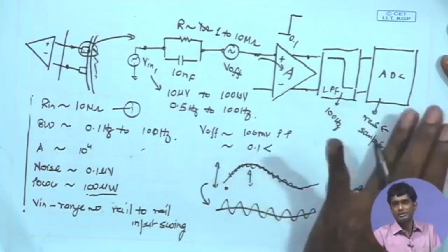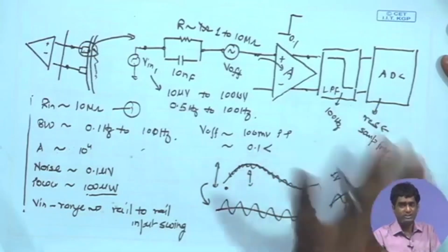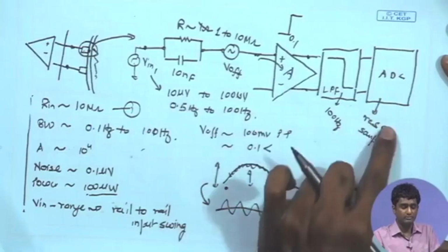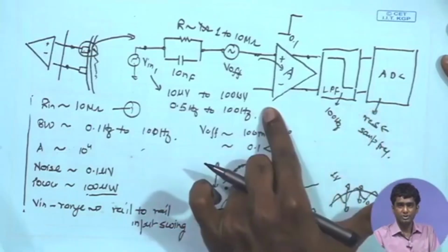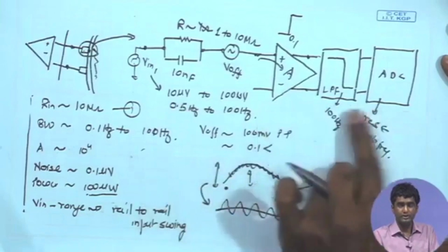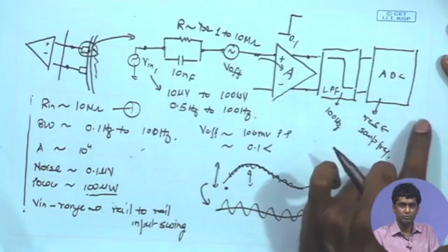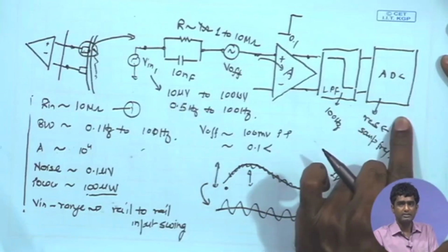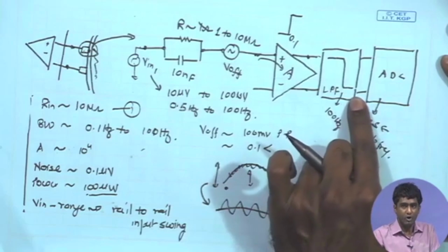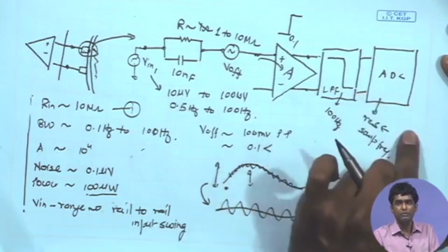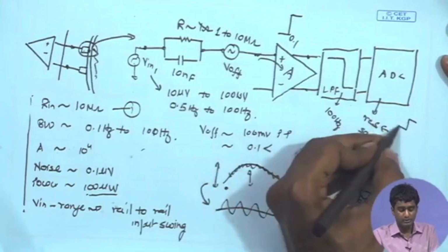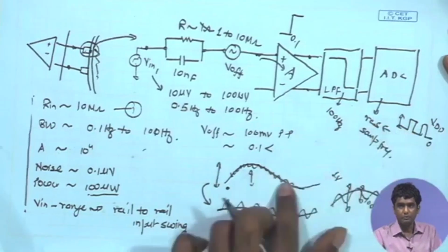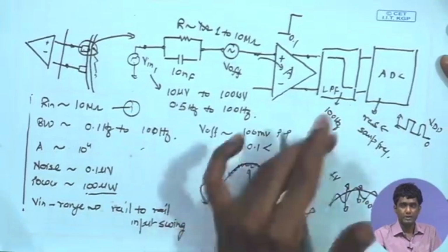Along with that, you have digital signals or metal lines carrying those strong digital signals in the vicinity of these analog processing blocks. They can also interfere with your analog processing chain. So, as we are going closer to the digital domain, the noise contributed by those digital components sitting close to this ADC is even stronger. As a result, the amplified signal also has a good chance of getting corrupted because of that common mode signal produced by these very strong digital signals having a peak to peak swing close to the VDD swing.